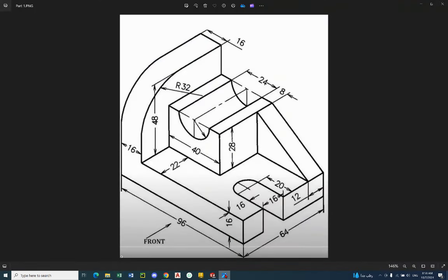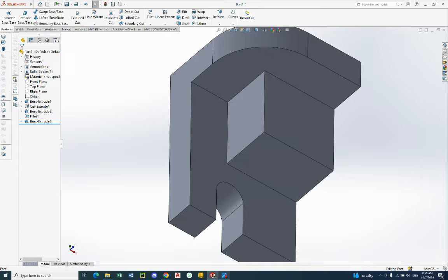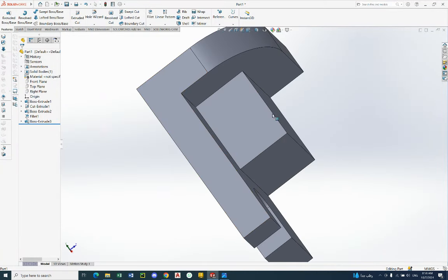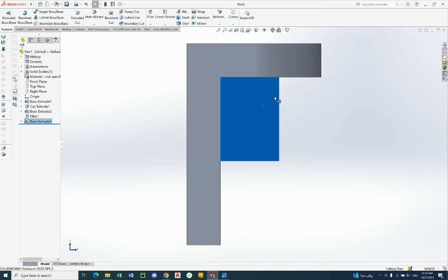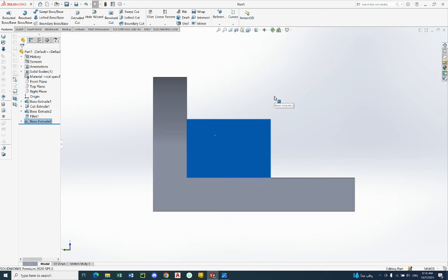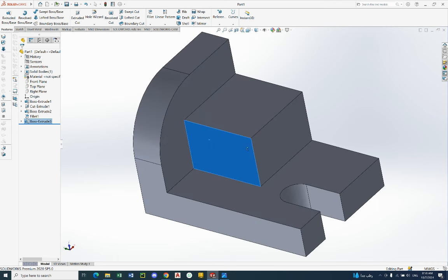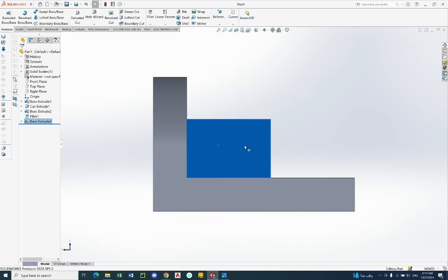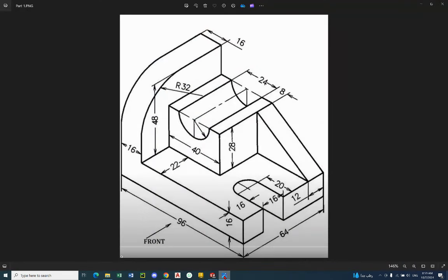Okay, of course we should update this cube to do this cut, the half circle cut. What to do in this case? I click save here, right click, normal to. I can rotate it here, right click normal. I can click alt and left arrow or right arrow on the keyboard in order to make it normal also.